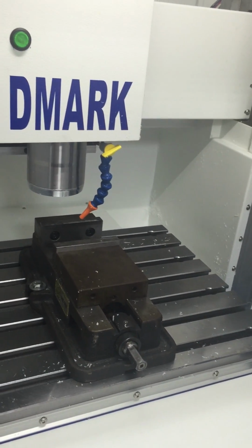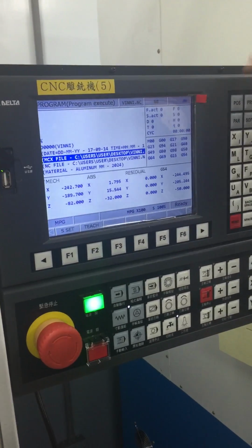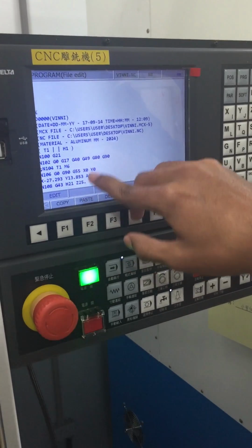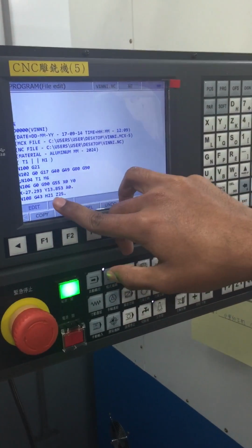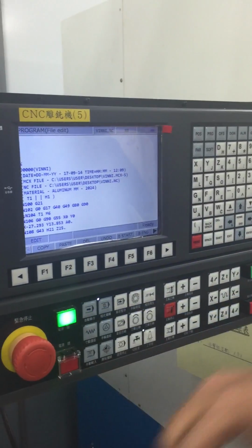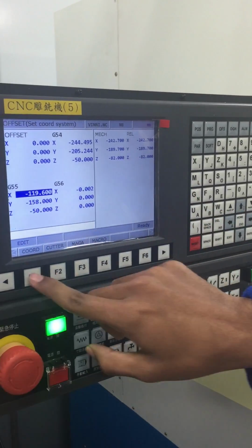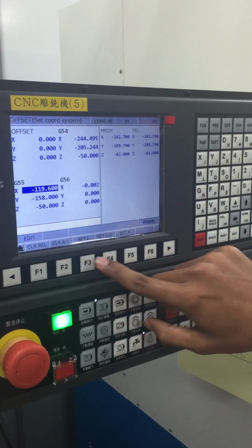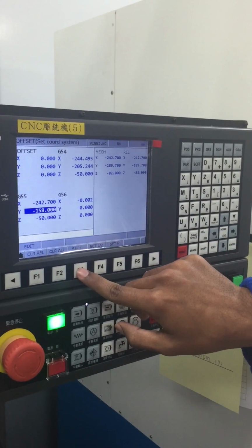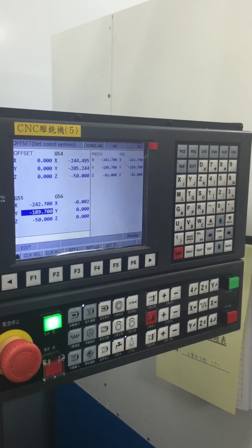And then after that, you gotta set your X and Y for G55. So you're at G55 because the program actually said G55 and H21 in edit. G55 is to set your X and Y coordinate when it is positioned there already. So you go back to offset, G55, let's set our X coordinate. So then you go to coordinate, auto, set L. You go down, and then you set Y. Alright, set L.